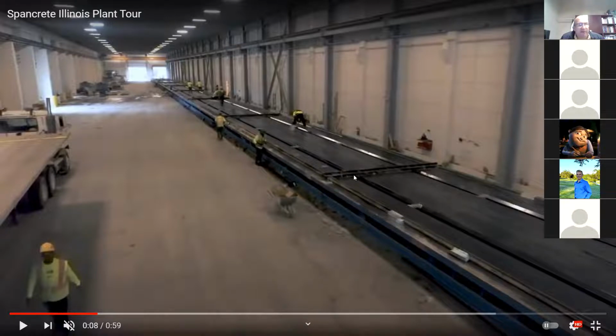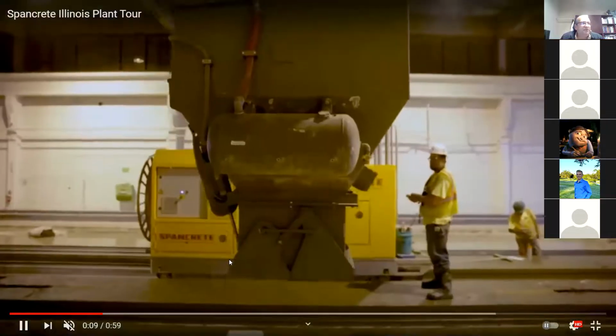And this is going to be one of the abutments, right? You have one abutment here, you have one abutment at the end. This is going to be like dividers. And then they put the reinforcing, they put the cables, they do the tension because it's going to be pre-tension. And after that, they put the concrete, they finish it.